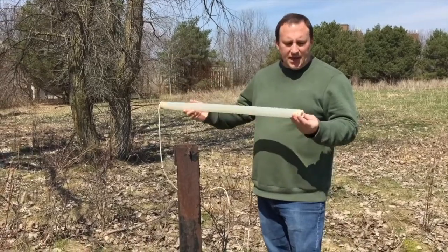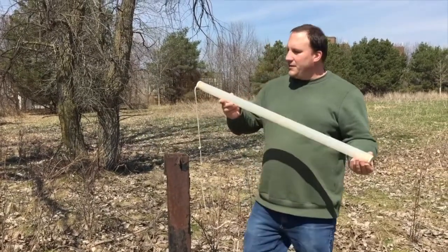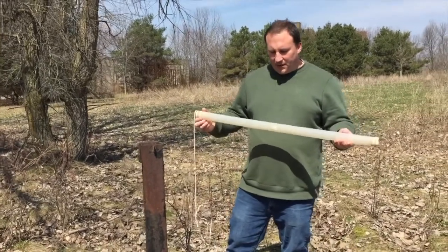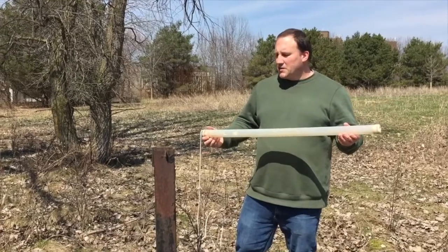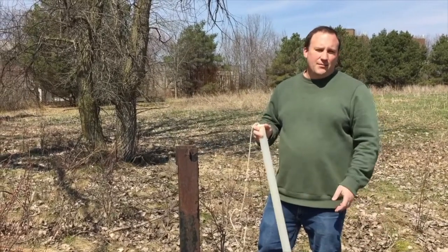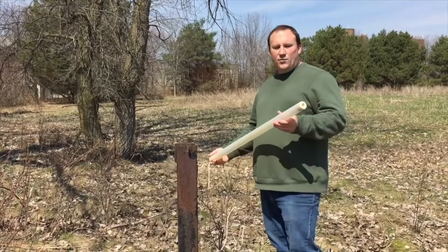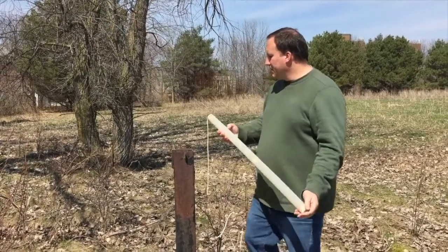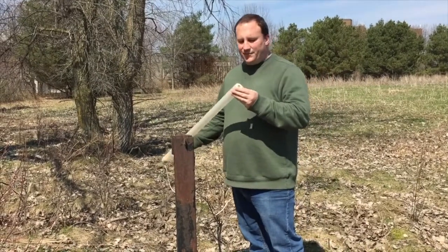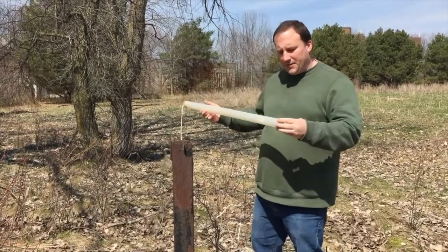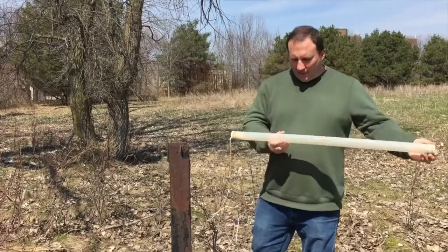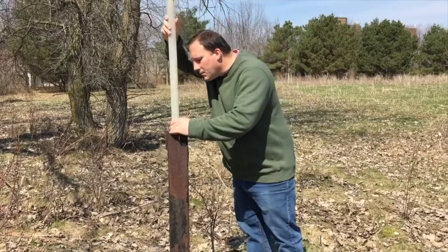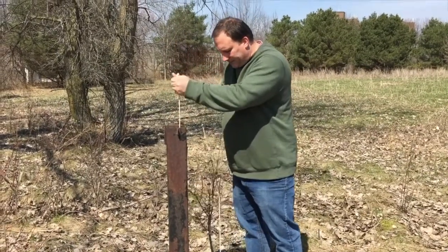This part of the exercise is going to be taking a bailer. This is a different kind of bailer. It's a plastic bailer. Normally these are things that are considered disposables. So you would leave this one inside the well if you had a contaminated well or something like that. But we don't have contaminated wells. We just need some kind of bailer that we can repeatedly use. These are something around the order of $15 or something like that. They're pretty cheap. So there's our ball for the ball valve. There's the hole. So I'm going to get some water out of this well.